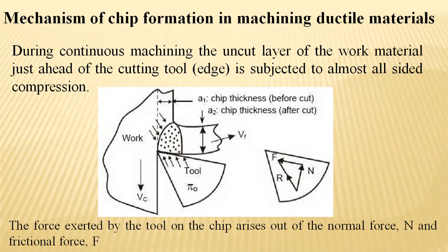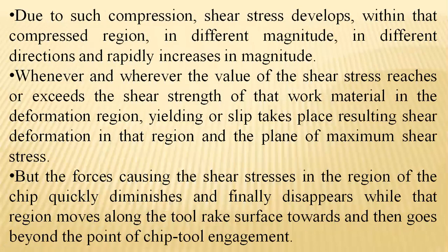So here, upon crossing the elasticity limit and plasticity limit, it will directly move on to the upper yielding point at the contact of this tool and the work part, so that the rupture conditions will be developed further. And then it separates the material from the parental material.